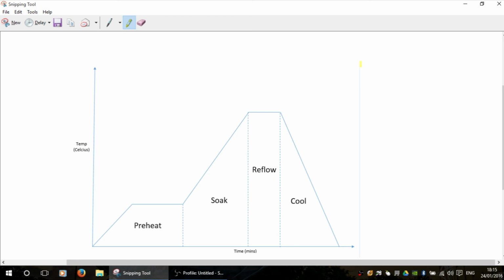And rather like watching popcorn kernels in a microwave, once it gets to that point, the BGA actually pops and you end up with little bumps all over the surface of it, and it doesn't look very nice. As soon as you do that, then you've got a bad BGA and you can't use it. So you've got to replace the BGA.